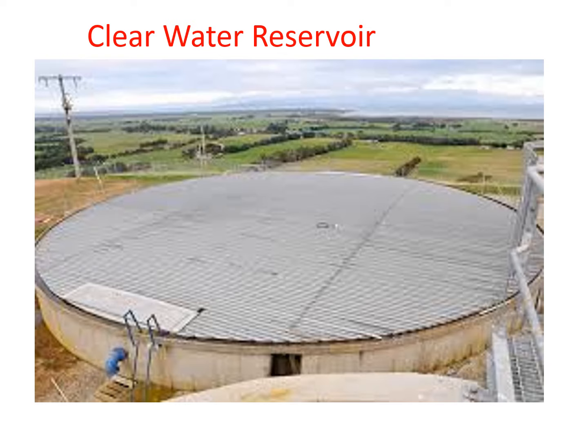So here this is the figure of the clear water reservoir, and this reservoir will store clear water. Generally here inverted pipes are provided of this shape, so that natural ventilation would take place, and they are bent because some birds or some impurities should not enter your water. That's why some bend is provided.